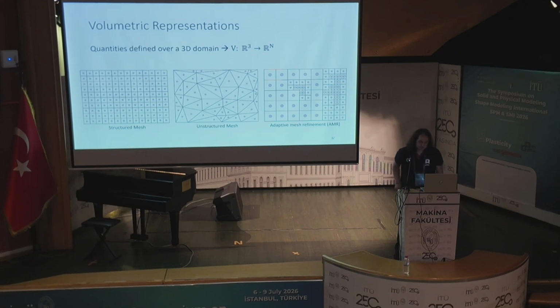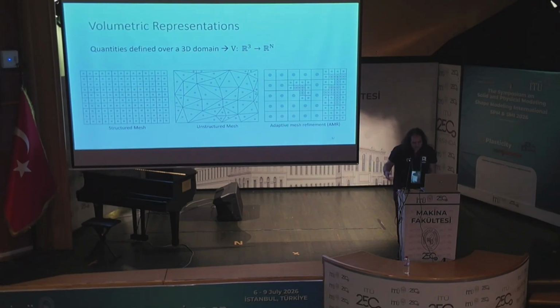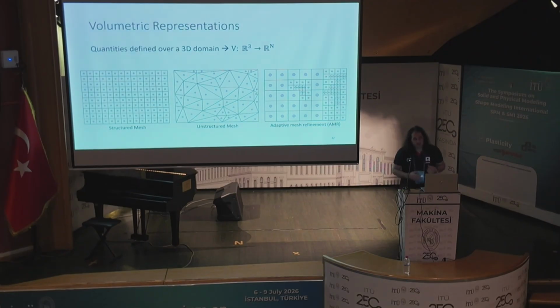Unstructured meshes are another method. We divide the space into polytopes, usually tetrahedral or hexahedral, and use that to perform the simulation and represent the volume. Unstructured meshes are good for representing the input simulation domain or geometries, but again, they do not adaptively refine when you do the simulation.